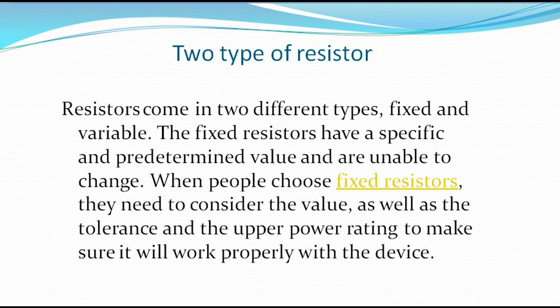That is why when people choose fixed resistors, they should consider the values as well as the tolerance and the upper power rating to make sure it will work properly with the device.